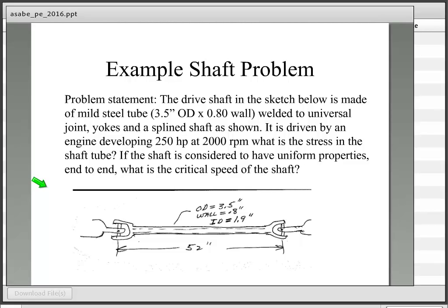That is where it would be undergoing, you'd have a speed which is at the resonant frequency of the shaft, which is not a good thing. That would be another definition of failure in the case of design of a shaft, because it would be unsatisfactory. You have a lot of vibration, a lot of noise, and so on. So there is a method of calculating that.